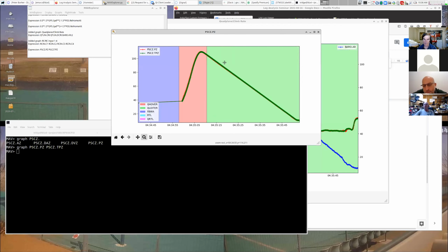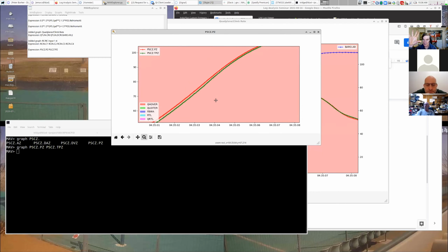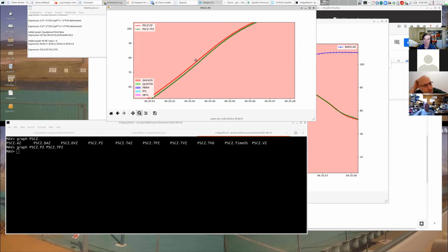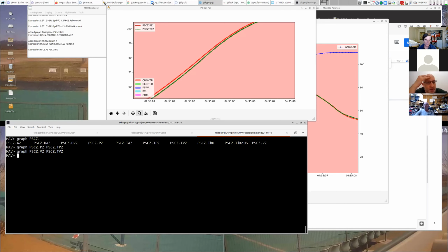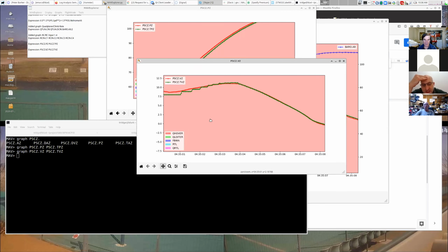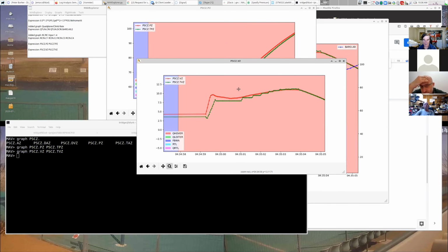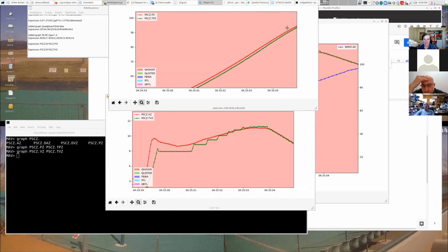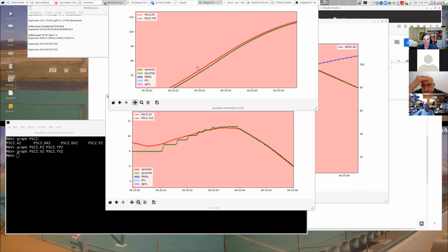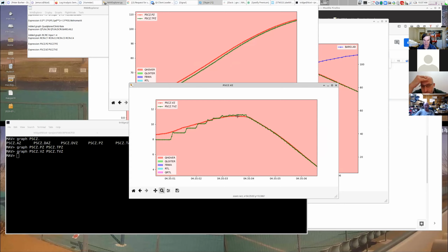We know that it's not that it was wanting to climb, so it's not a bug in the demanded height, it's a bug in a lower layer of the controller. It's a nested PID controller where it's got a position controller for height, then a vertical velocity controller, then a vertical acceleration controller. First of all, our position controller is saying we want to be lower. Now let's look at the velocity controller, so let's look at VZ and TVZ. We can see here a bit of an odd thing with some stepping. But the key thing is that, at least as far as this major climb, at least in the first part, the target velocity is below the actual velocity. It does go a little bit higher here, so that's a bit of an anomaly, but most of the time the target velocity is below the actual velocity.